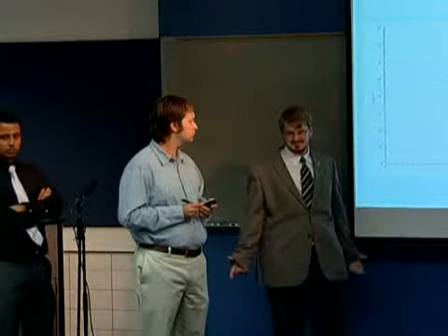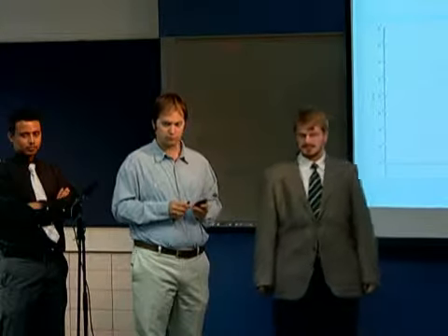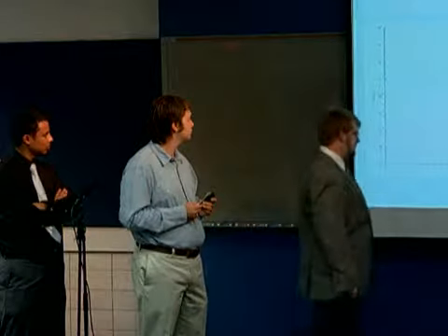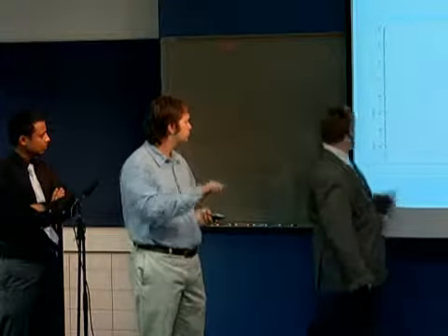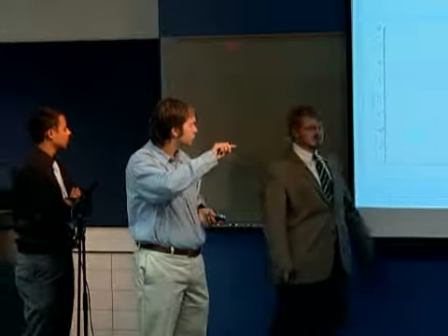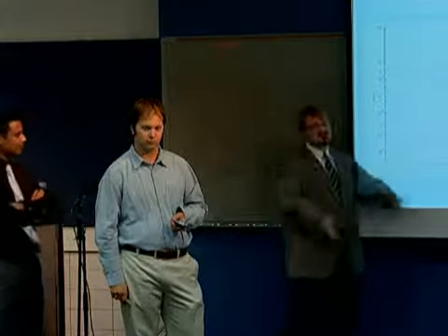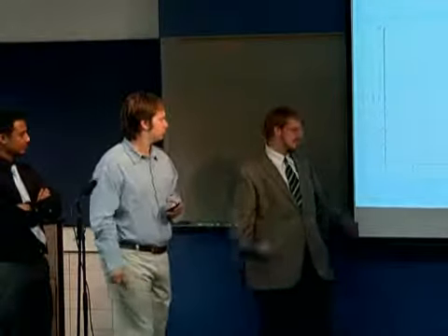Just out of curiosity, how did you obtain the bit error rate below 10 to the minus 6 in simulation? You mean these? Somewhere below 10 to the minus 6. You let it run for a few hours overnight? Okay, so you're talking about transmitting like 10 to the power 8 or 9 bits. Yeah, the simulation just keeps on doing it for us, and I've run simulations overnight just to let it run.